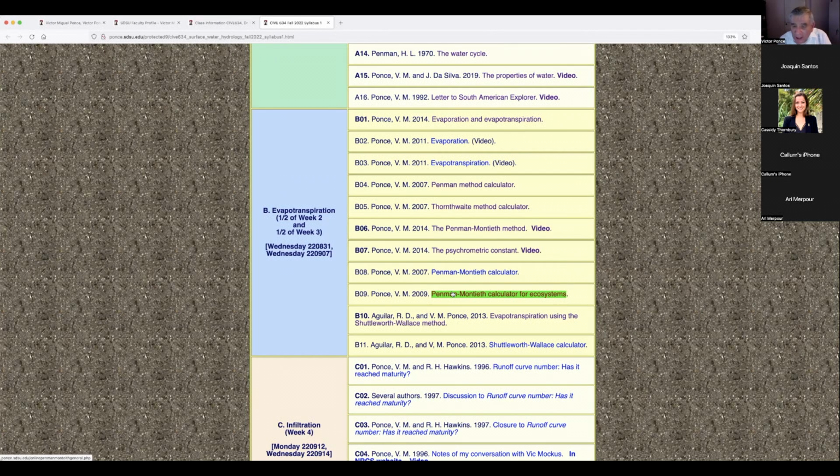Well, in the Shuttleworth-Wallace calculator, there are 5 resistances, because purportedly it will do a complete calculation across the board of evapotranspiration or evaporation types, because we know for a fact that there are 3 types of evaporation, and they're physically and chemically different. There's from surfaces, from water bodies, and from vegetation. And Shuttleworth-Wallace make the best effort to account for all 3.